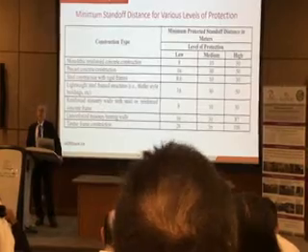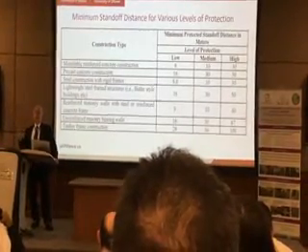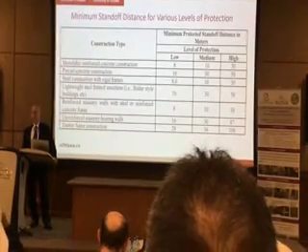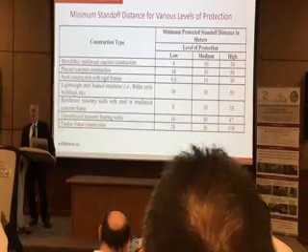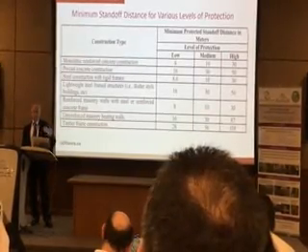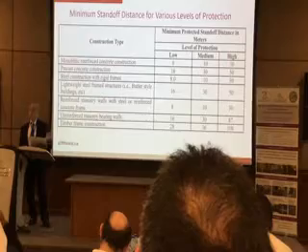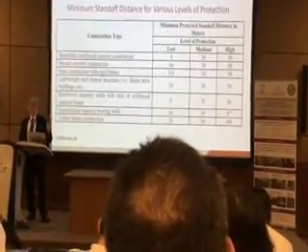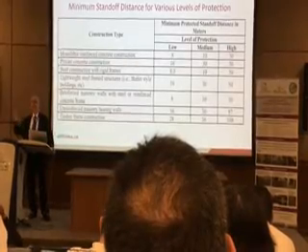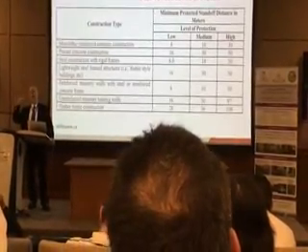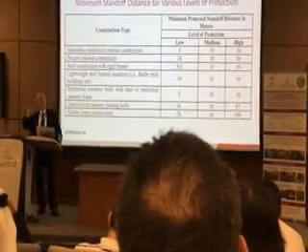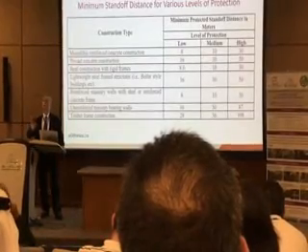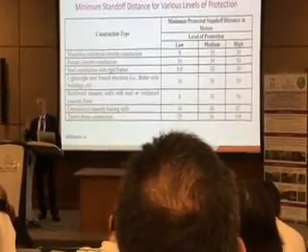So there are recommendations for standoff distance, and this table lists them. This is taken from the Department of Defense, from the US Army. As you can see, this is indicated as a function of material type. And we will emphasize this. Why? Because blast is a dynamic effect. It's not like applying a static load, which would then be reacted to by the resistance of the building. But the moment there's dynamics involved, there's an inertia force resisting it, right?